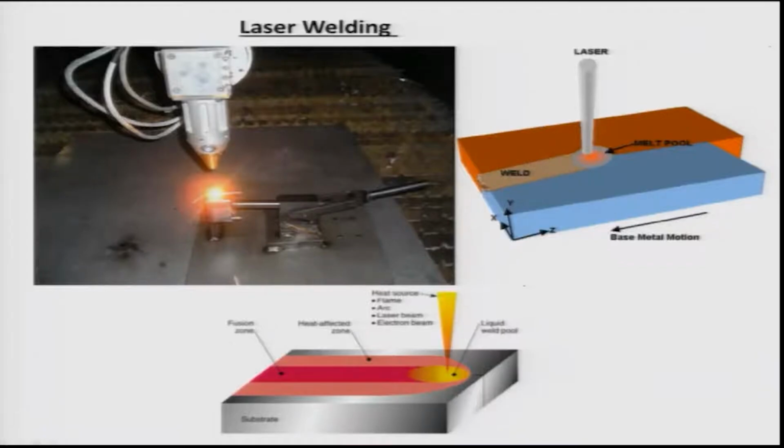Because of that, a weld pool or liquid pool is generated, and as the sample moves, with the laser remaining stationary, the position of the laser beam on the surface also moves. Because of that, the pool gets solidified at a certain rate. So the growth of the nucleating phases forming at the two joining surfaces is the most important aspect.